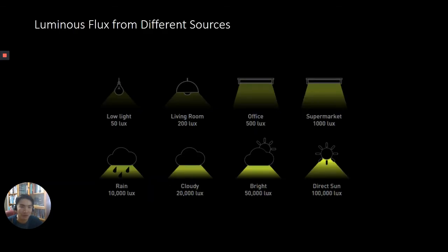You can find some range of lux levels achieved by different light sources here. Notice that the lux level for interior lamps ranges between 50 to 1000 lux. The outdoor illuminance value achieved by solar power is much higher than that, by at least a factor of 10.